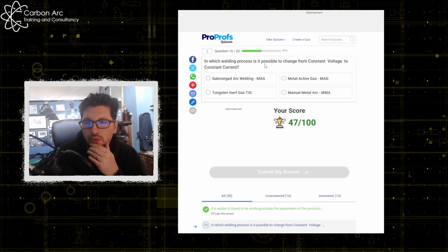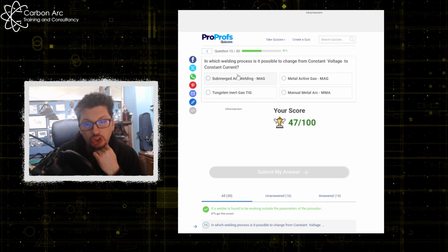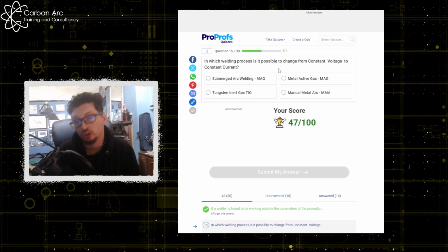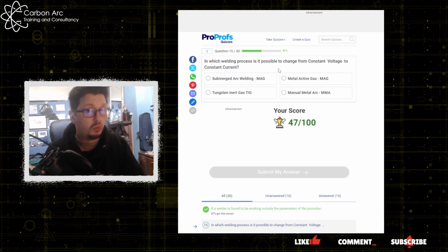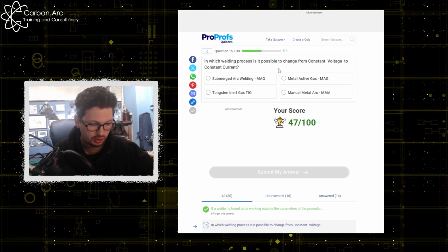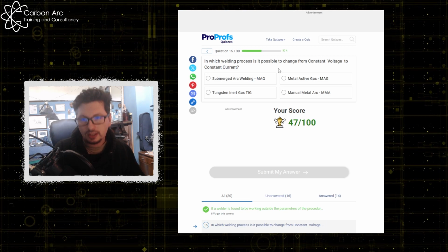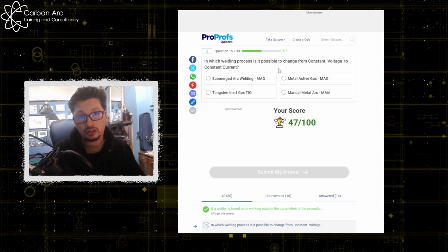Which welding process is it possible to change from constant voltage to constant current? So this is your flat characteristic and your drooping characteristic. Some processes use one, one uses both. So we've got TIG welding using drooping characteristic, constant current.